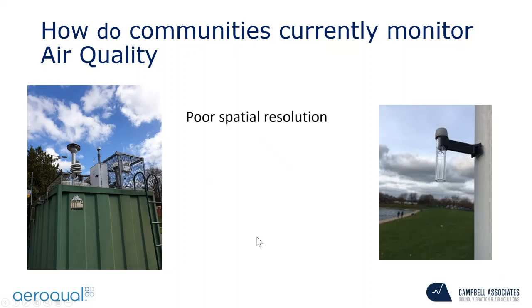We are also using diffusion tubes. These ones are inexpensive to deploy, but they need people to go on site to deploy them and to collect samples every 2 to 4 weeks. And then we will also have only the average for this period of 2 weeks or 4 weeks. So these will offer poor temporal resolution.